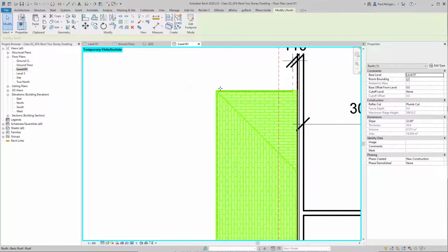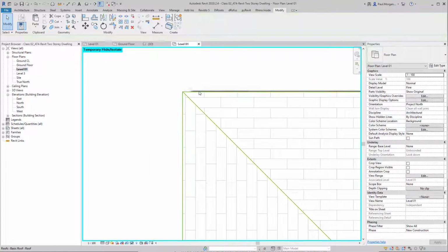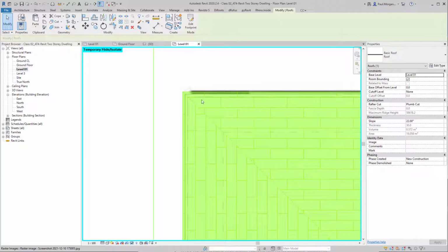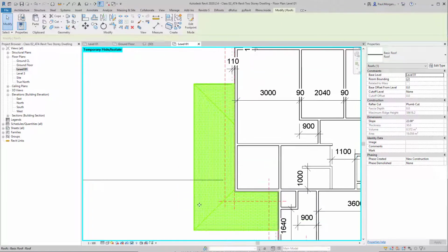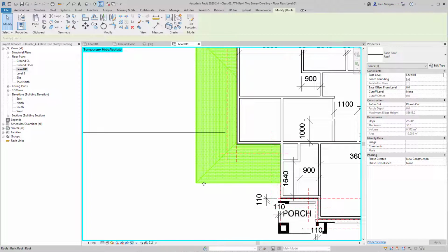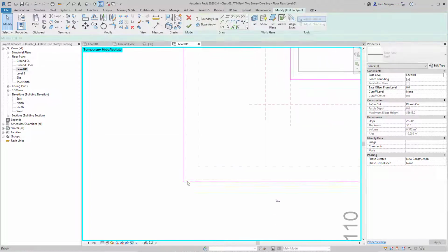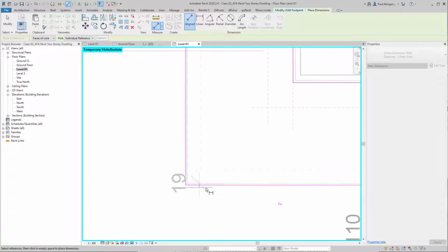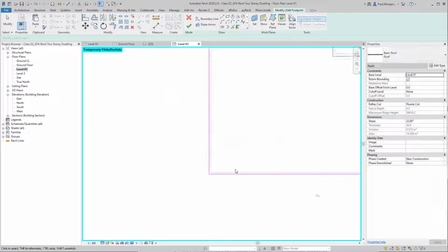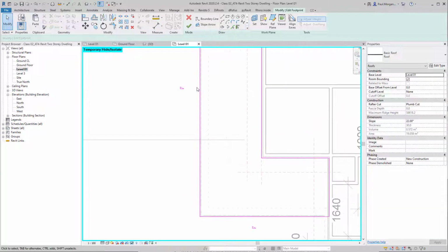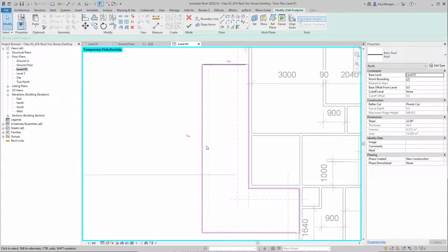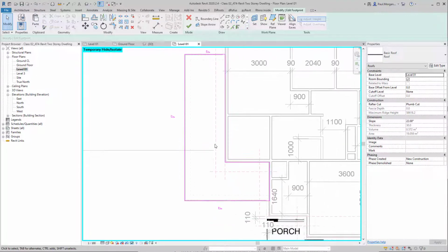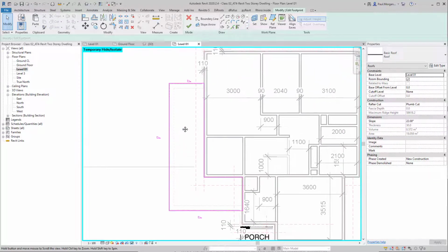So there's our roof there, and it is aligned to the very outside of our garage walls. In fact, I think it might be slightly overhung. Yes, it is. It's only 19 mil overhanging the double brick wall on the garage, and that's because we need a little bit of room to put our fascia board on there. So that's the sketch for our hip and valley, or really just our hip component of the garage.